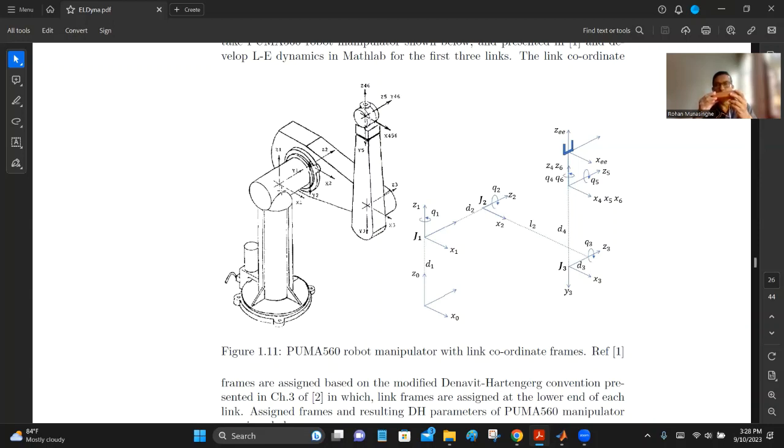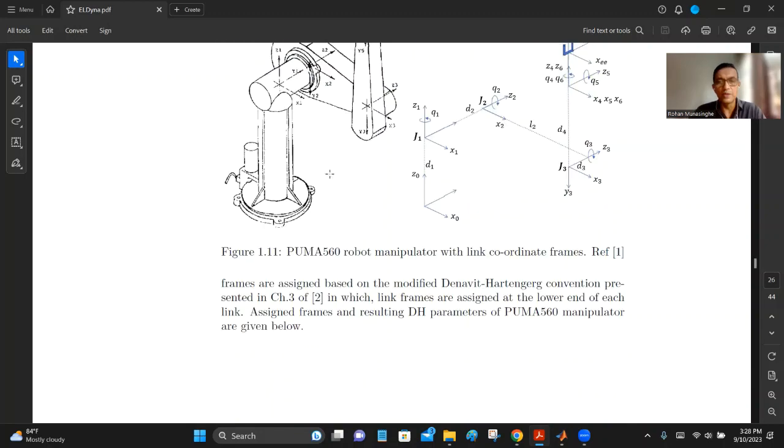And of course, weight is there anyway, but if it is vertically acting along the link, the weight also is not something that the motor has to bear. The motor has to provide the rotational motion, whatever torque is required for that. Therefore, mass doesn't get in the way for the first link only. The other links, you need mass because they're moving linearly, okay? Right.